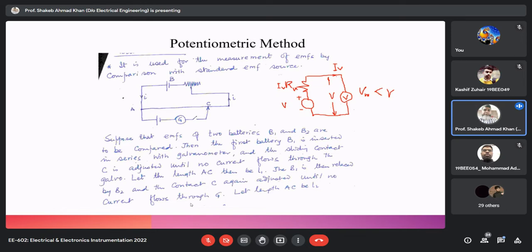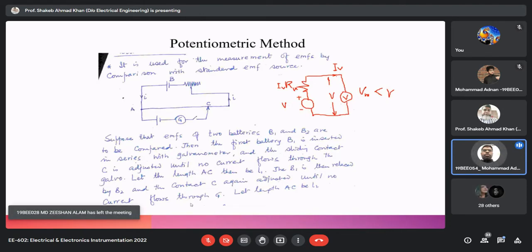Can anyone tell? The potentiometer is a three-terminal resistor with a sliding or rotating contact that forms an adjustable voltage divider. Potentiometers are commonly used to control electric devices such as volume controls on audio equipment. They are also used in joysticks. It is rarely used to directly control significant power, since the power dissipated in the potentiometer would be comparable to the power in the controlled load, sir.